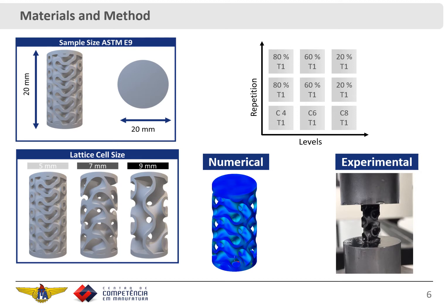So we can see in the figure on the left that we have three configurations of lattices. The first configuration is a weight reduction, then less weight reduction, and we have aggressive weight reduction with a 9mm cell size. I'm only varying the cell size. I'm not working with the thickness or the bias of the lattice structure. And I made a DOE, a design of experiment, with 3 repetitions of each cell, and then we will perform a numerical and an experimental study of these gyroid structures.